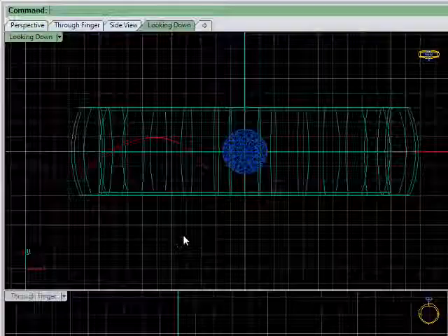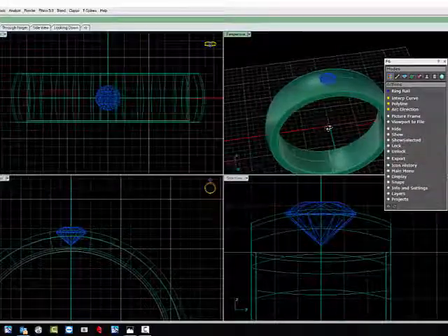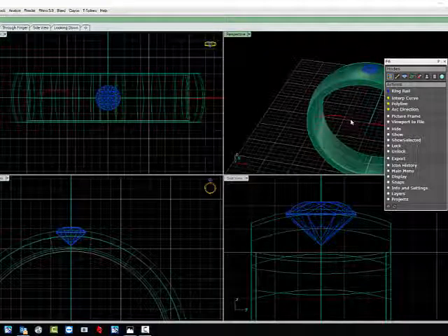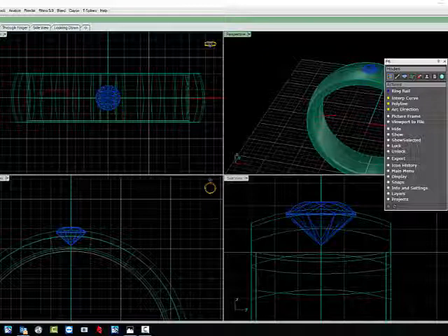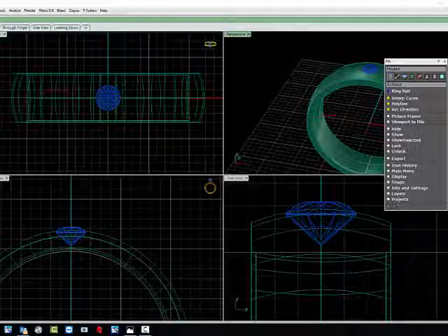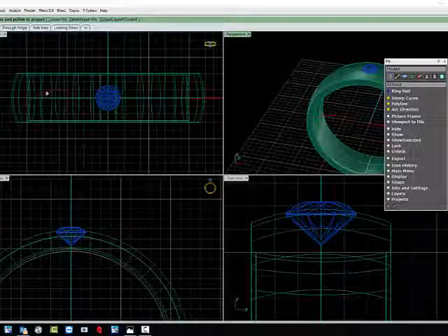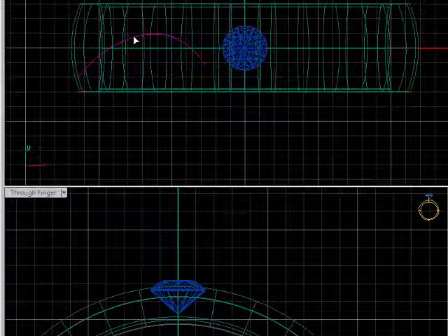Okay. Now, as you can see in this viewport, this is now down here, which isn't an awful lot of good. So we've either got curve from 2 views, or you can actually just project it. So if we come up to this section here under the curve menu, under the top page, looking through some of these, you've got pullback and you've got project. So if we hit project, select the curves and the points to project. Well, it's that, and we hit enter.